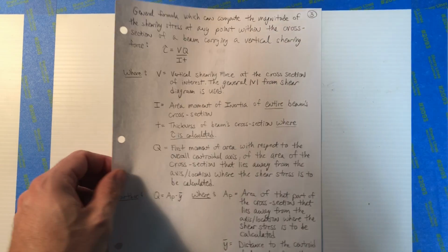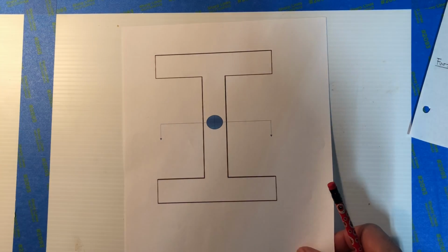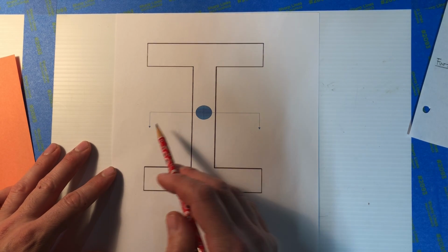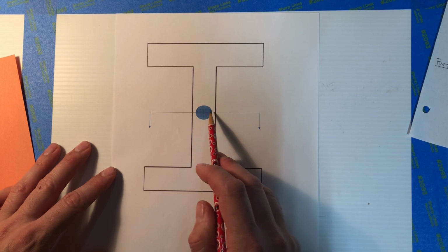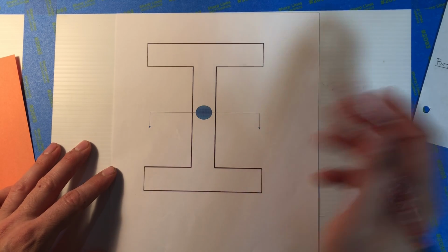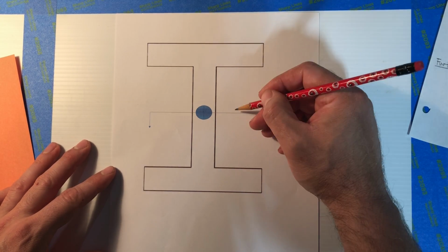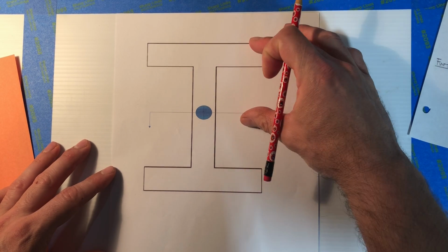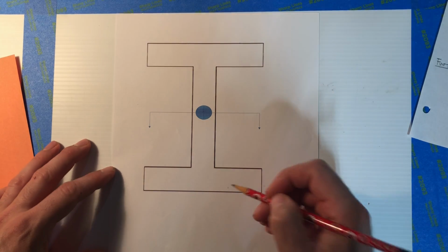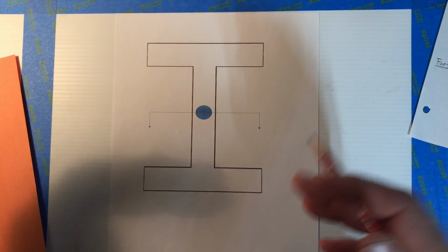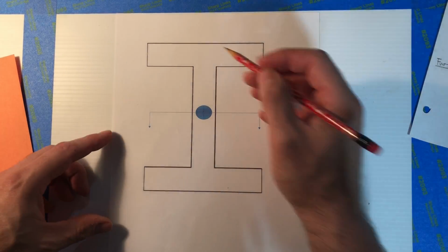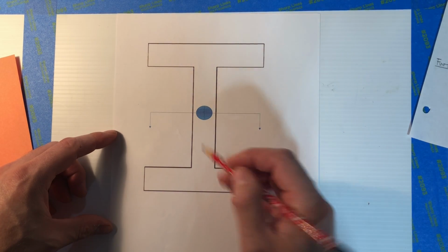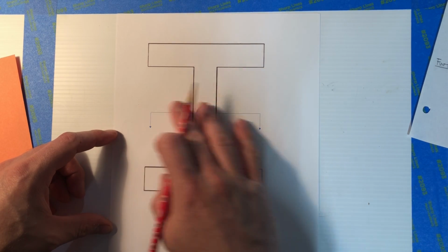Basically, here's a little sheet I made up. This is an I-beam, right? And we're going to find in a second that unlike bending stress, the shear stress is maximum at the centroidal axis, or the neutral axis. Bending stress is the opposite. Bending stress is 0 here, and as it gets further away from the beam, the bending stress is maximum here and here. In shear stress, it's exactly the opposite.